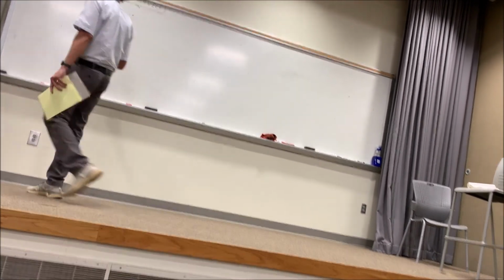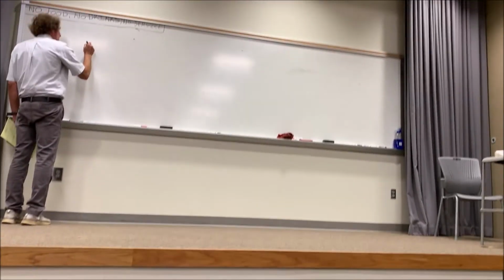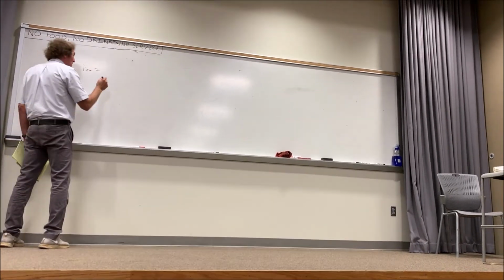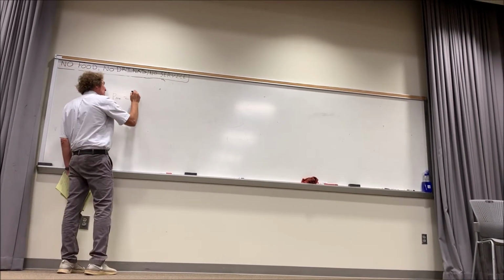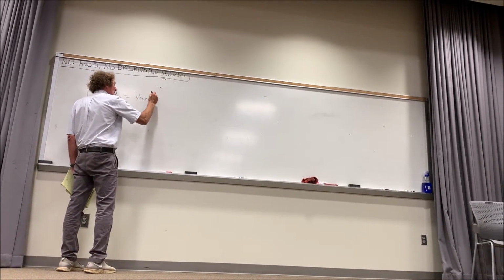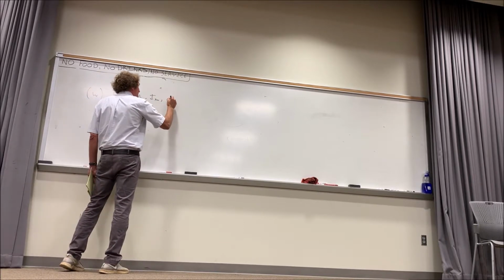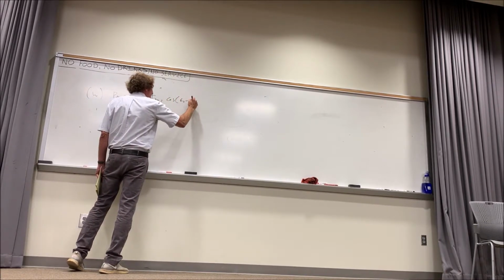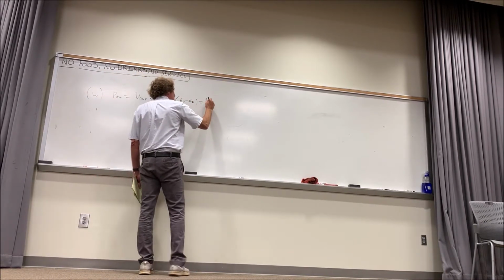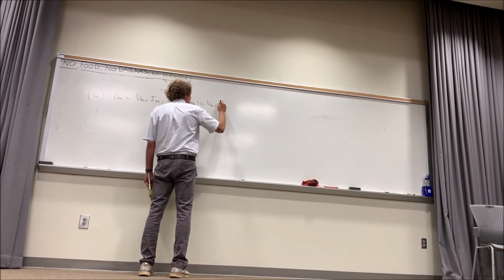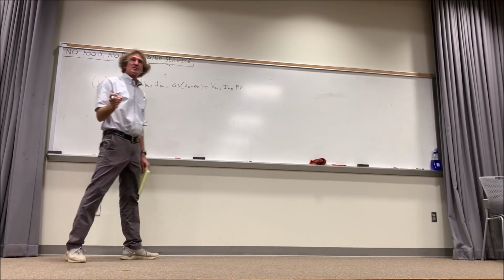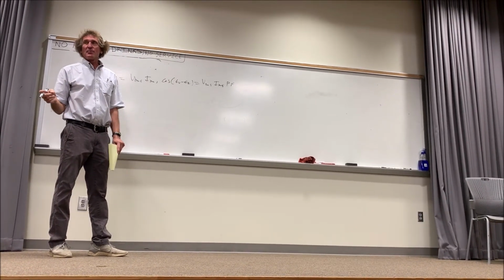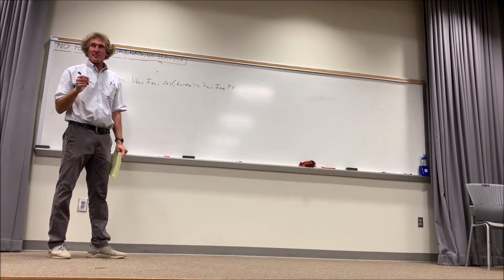When we talk about power, average power, P average, remember, this is in watts or kilowatts, right? That's equal to VRMS times IRMS times the cosine of theta V minus theta I, or it's equal to VRMS times IRMS times the power factor. Please write this down. This is going to be important. You will get hurt if you don't understand this.